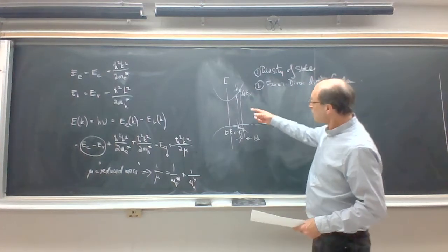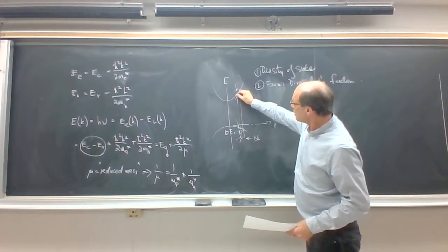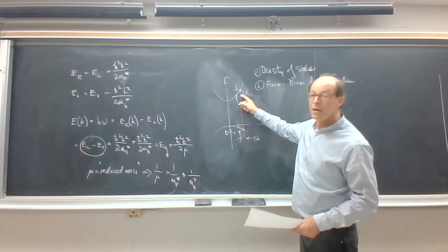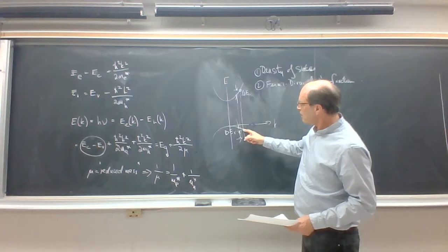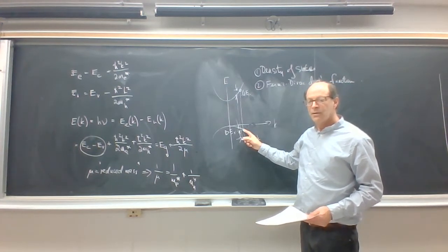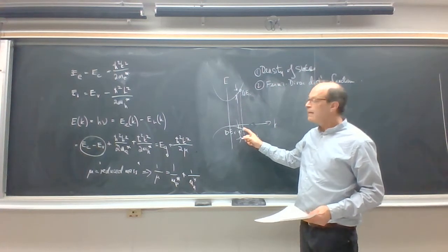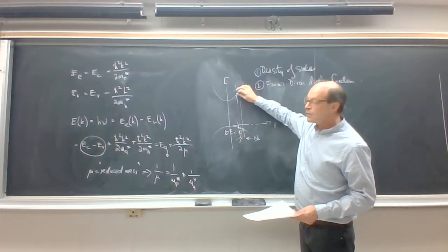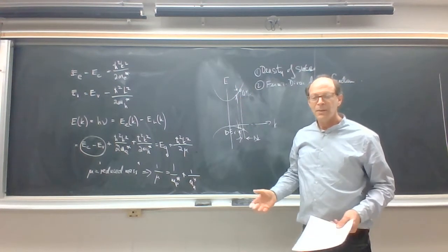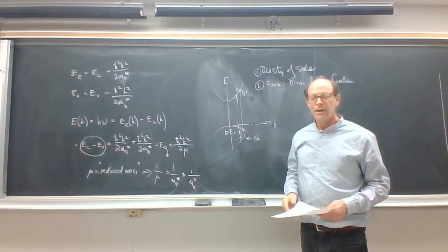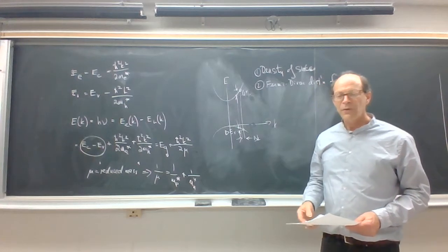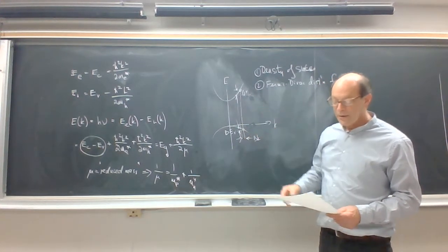And the size of that range really depends on delta E versus delta K in the conduction band, plus it depends on delta E by delta K in the valence band. So we really have to add together the delta E values in the conduction band plus the delta E values in the valence band to get the entire range of energies that can produce, which will represent the photon energies that get produced by that range of